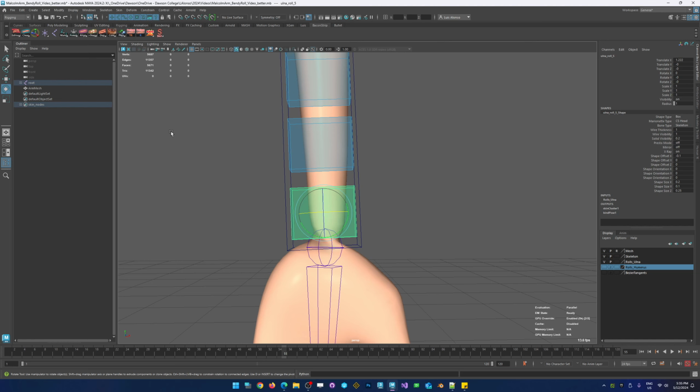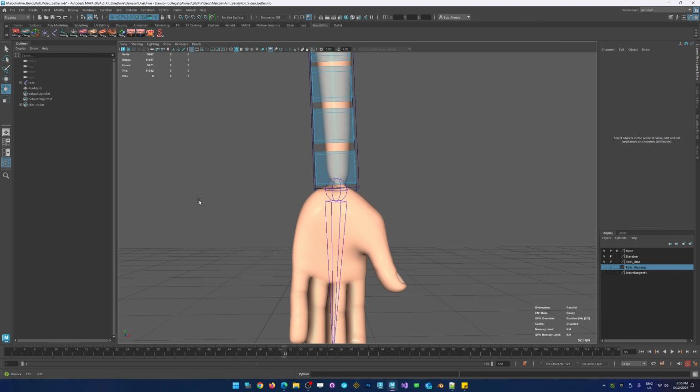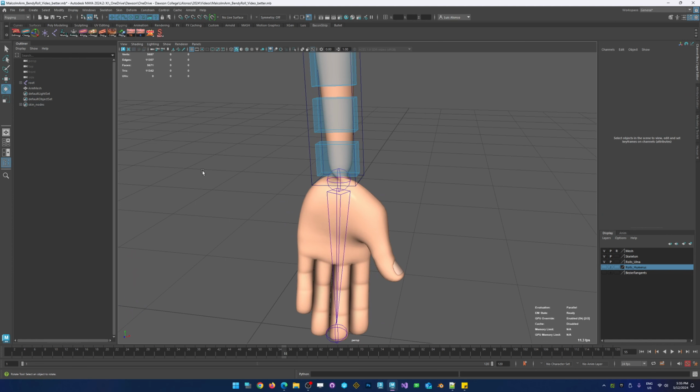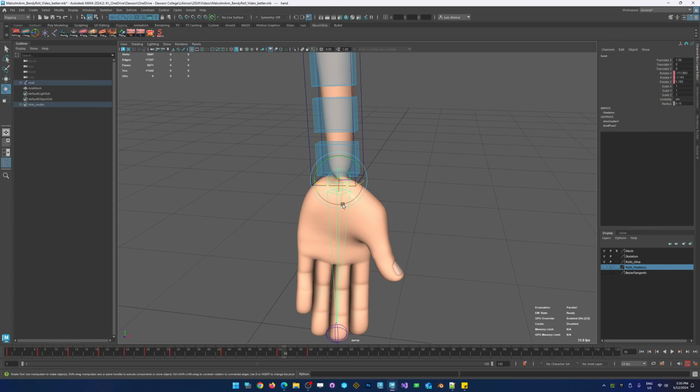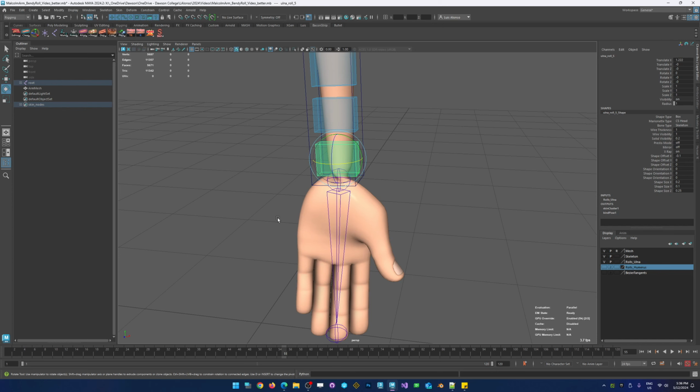So by adding more bones, we're adding more values that it can use as a reference. So I can do that type of thing, and then that, and then that. But getting the roll value out of this hand to go into these objects, well, that's a bit tricky, isn't it? So we're gonna start with the first approach that is quite common, and that's to simply take the rotation value of the hand on the x-axis, just the x rotation, and throw that onto this bone here and make it spin a certain percentage.